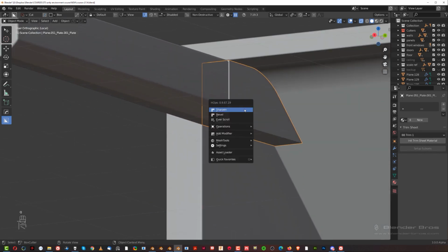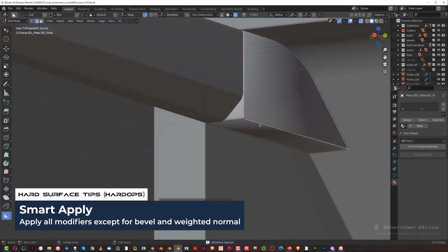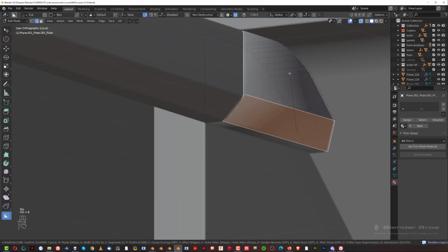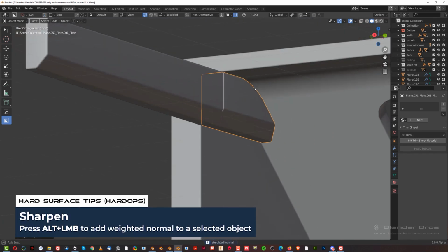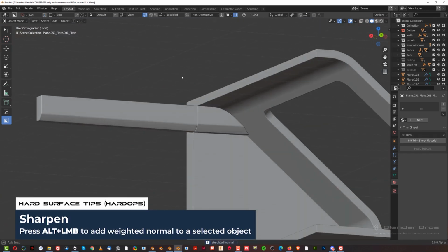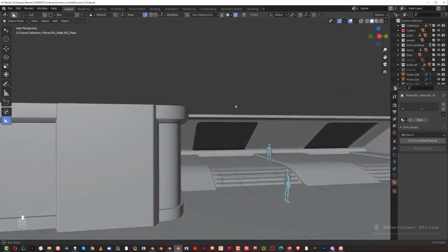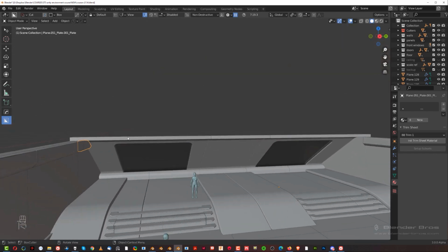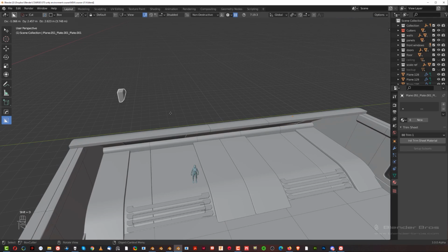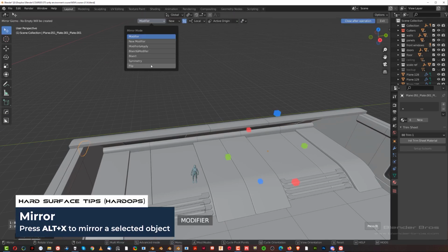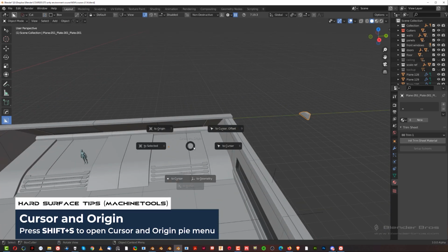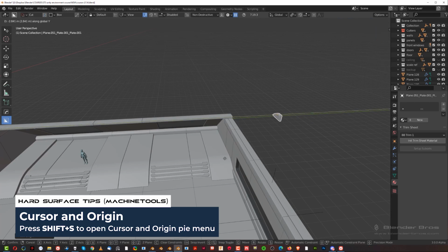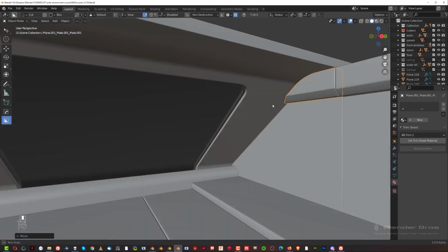and then we're going to apply this. So operations and multiply, and we're going to grab this one and chamfer this. There you go. And then sharpen, and we got this piece in a corner, which is quite important. All we need to do is do the same thing on the other side, or we need to flip it. So we can Shift D this, Alt X, modifier, flip, and flip it to the other side. Then Shift S to geometry, and G, Y, and move it here, and boom, sorted.